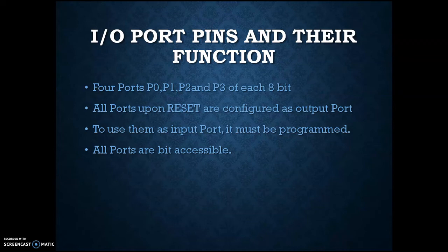Take port 0, which has 8 pins. If we want to make any particular pin, say the second pin of port 0, an input port, we can access it, or as an output port we can also access it. That is bit accessible.